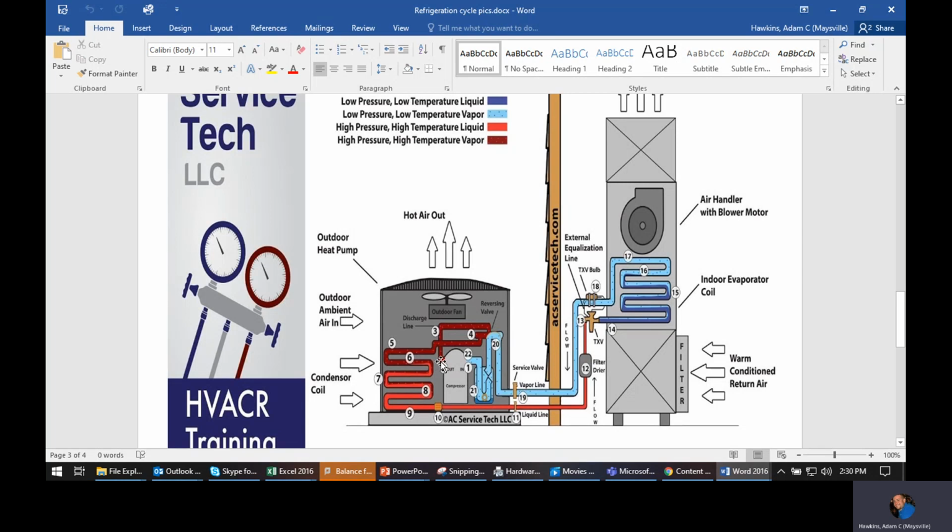In the condenser, you actually don't have anything that starts that process other than just blowing a fan across it and removing heat. So in the condenser, the first thing that actually happens, and you may see this on a test, is what we call de-superheating. So if I superheated it, and superheat is all sensible, before I can ever start to condense, condensing being all latent, I have to remove the superheat.